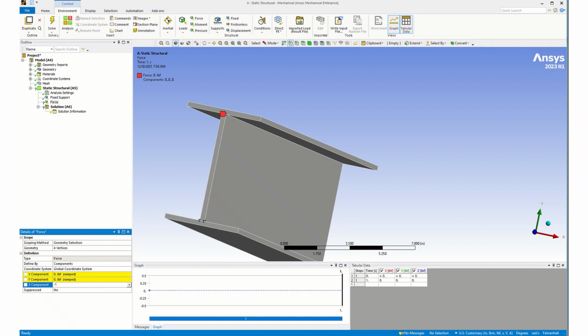And I'm going to enter that -1 because then when I go to compute my eigenvalue buckling loads, I will compute the lambda, or the multiplier, and that multiplier will be the critical buckling load. I won't have to come back and multiply it by a static load of something different than 1. So when I'm doing a buckling analysis, I usually put this static load in the first module equal to a -1 to give it a compressive unit load. So now I've got that entered. I can go ahead and hit enter. You can see that I've got green check marks all the way through now.